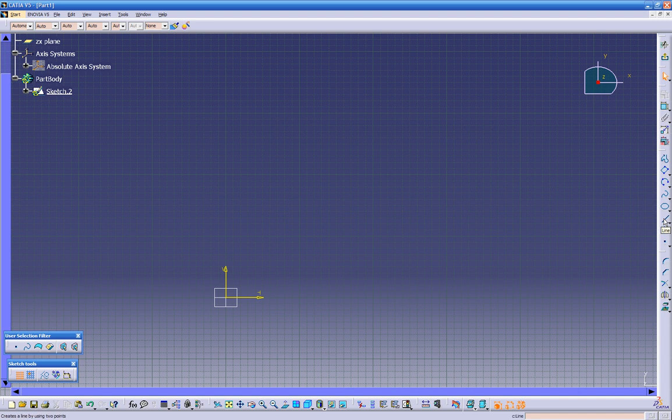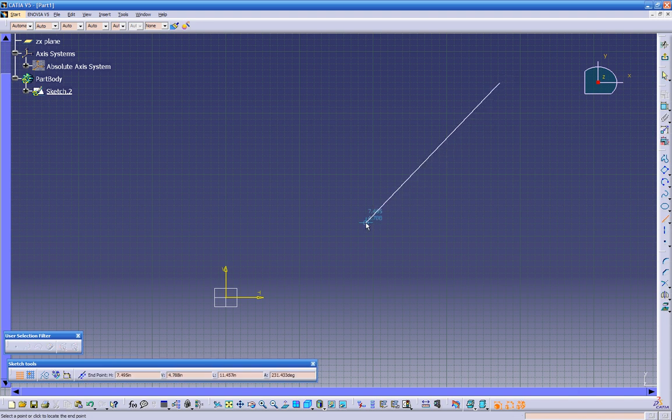But let me show you this quick. This is pretty handy. If you click on this icon only once and you click on the line, you just create only one line. You cannot go any farther. See, this is deactivated. But let's see, if you double click on the line, create one line, you can keep on going. If you watch this icon right here, it's activated. As you see, it stays brown.